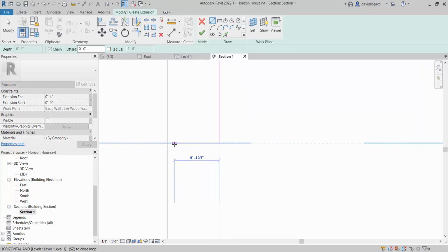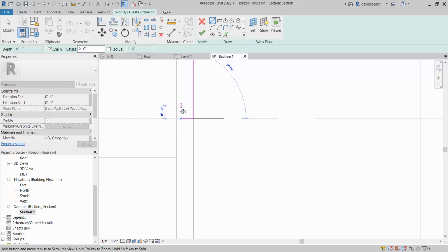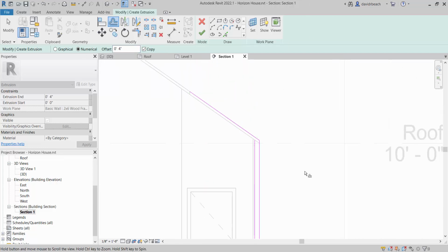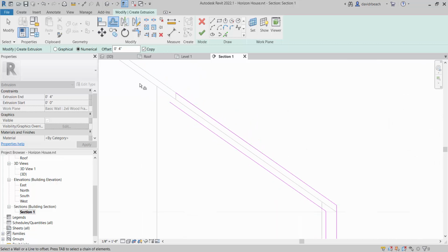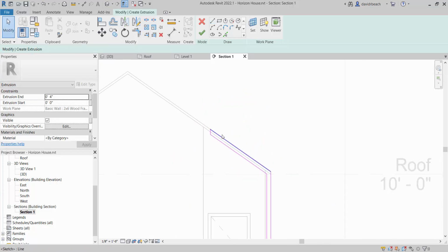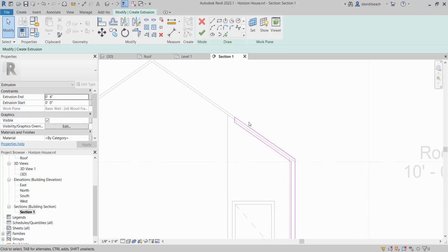I know my mullion, my default mullion, well, I'm just going to guess here. Let's go 4 inches thick. So then I can use my offset, 0.4 for 4 inches. So I'm going to offset that mullion in 4 inches, down 4 inches, and then I need to connect this piece together. And if you'll notice, that mullion is thicker than the roof, and that's okay.